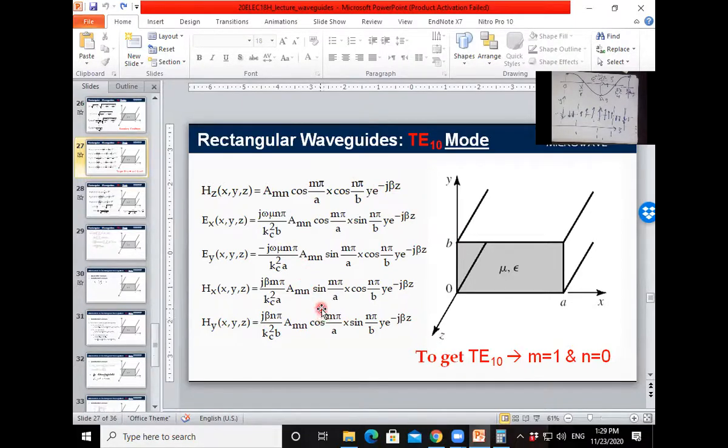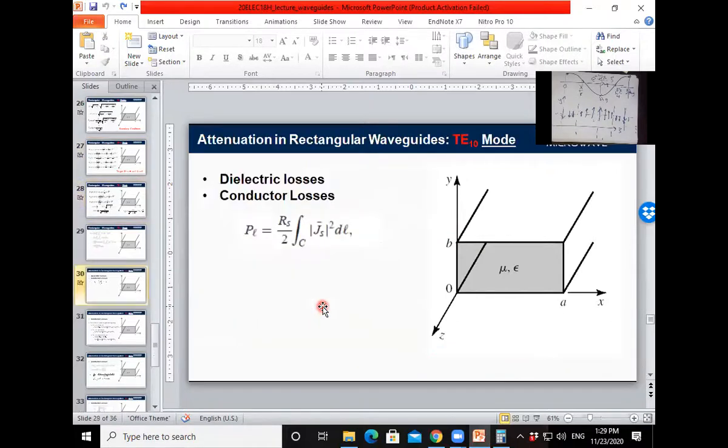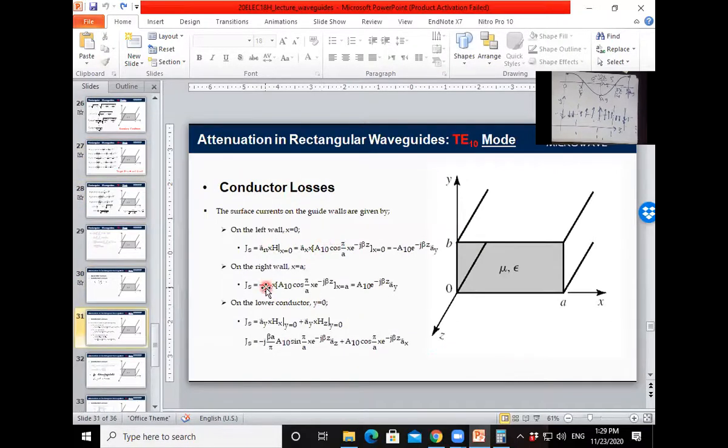And then you can plot the electrical field component and the magnetic field component, and also calculate first the surface current using the same equations, and also calculate the total surface current in the four faces of your rectangular waveguide structure, depending on your structure or on your mode, TE10, TE01, or whatever it is.